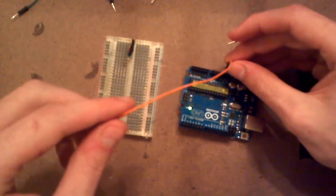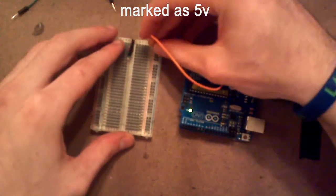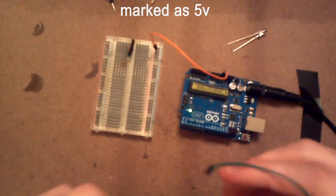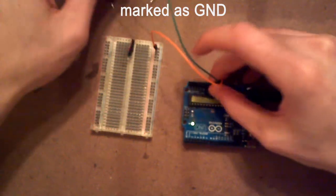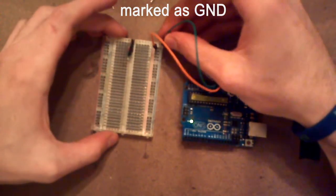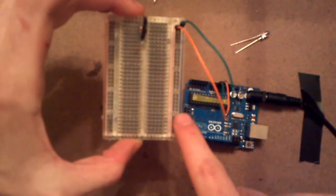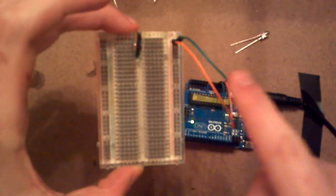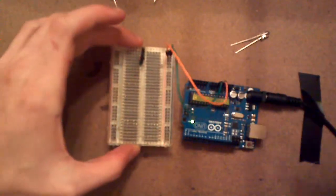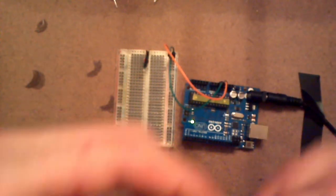So I know you can't see this, but this fourth pin in this jumper is the voltage line. It actually says it right next to it in a very tiny text. And then the one right beneath it is a ground line. So I'm going to connect power to power and ground to ground. And you can see there's like a red line and a blue line on this. And I've got my warm color jumper hooked up to the red side and my cool color jumper hooked up to the blue side. And I can test that I did this right by plugging in my LED.